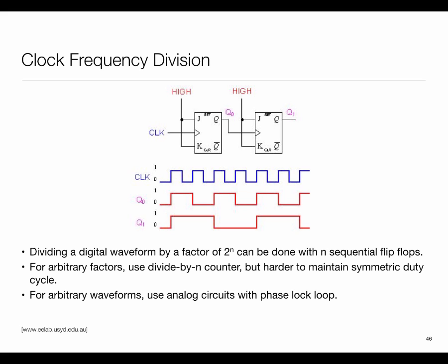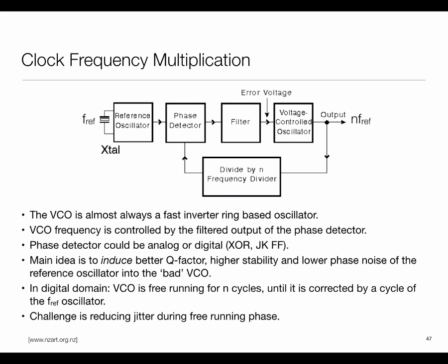Bear in mind that even though we operate our processors at, let's say, 2 gigahertz, 3 gigahertz, there is no such thing as a 1 gigahertz crystal. Your crystals are 40, 50, 100 megahertz. So internally, you have to multiply things out. And that is done using these things called PLLs, or phase lock loops. Some of you may have seen this, but for those who haven't, the basic concept is like the following.